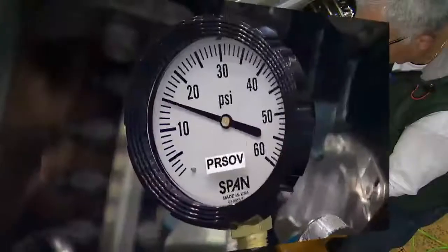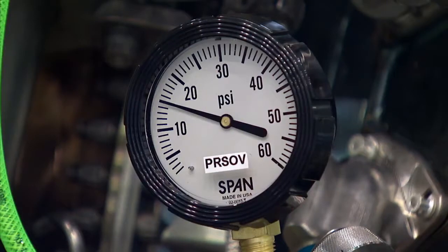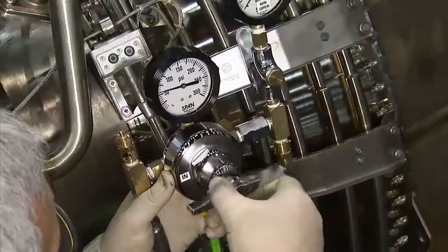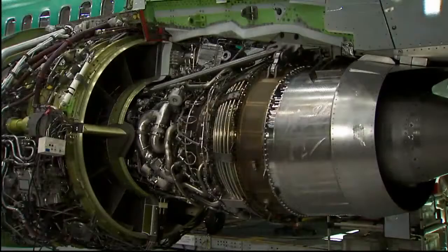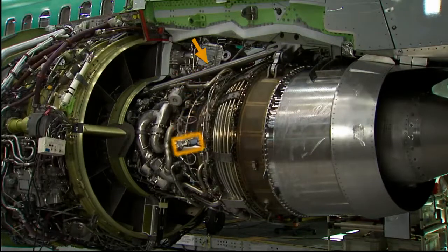If the control pressure is still low, then there may be a leak in the 450 sensor or its sense lines. To isolate the 450 sensor, turn off the supply pressure. Then disconnect and cap its control pressure line up near the left side of the pre-cooler.